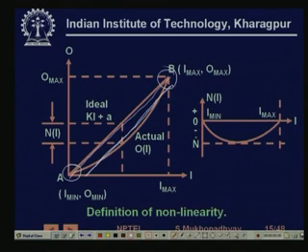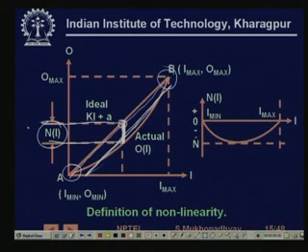However, in some cases you can perhaps use this line, that's a simple thing if it does not matter. So basically, whatever the line, once you have fixed the line, the nonlinearity is this deviation. Here it has a maximum deviation. So the nonlinearity spec, which we actually refer to as a linearity spec, is the deviation from that line.